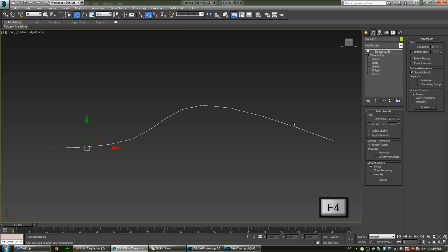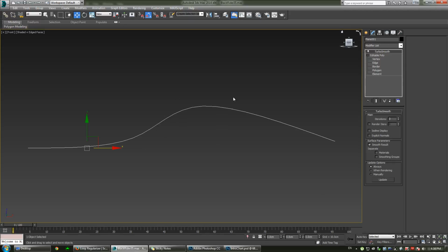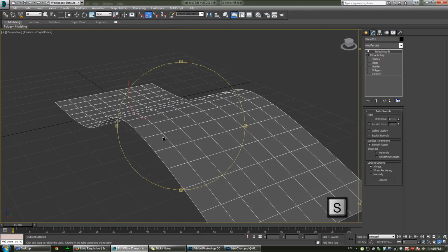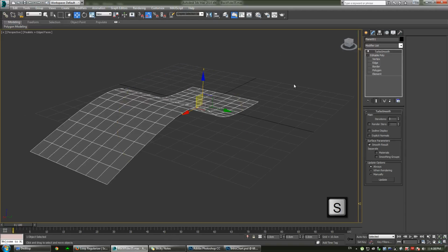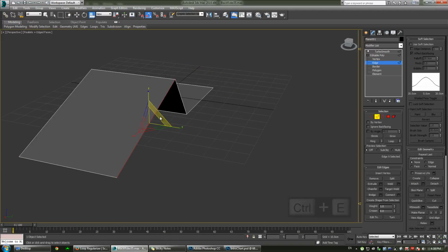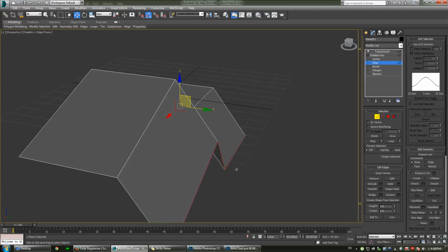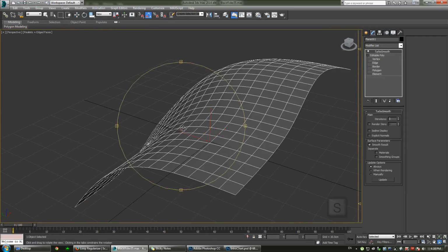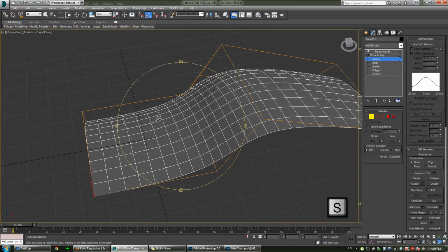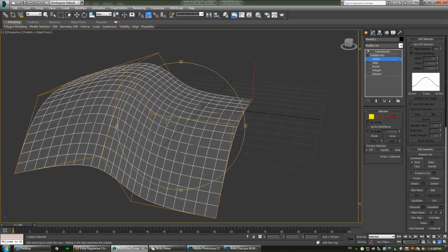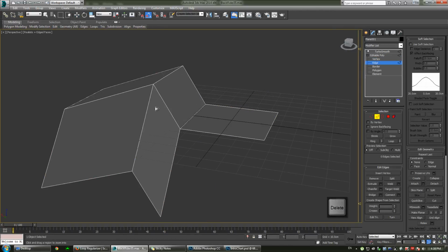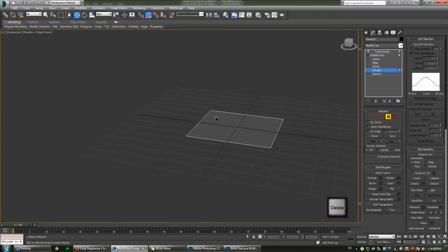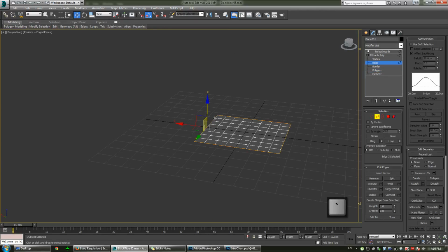And you can see I've got this mesh from side on, and it's just averaging out between those two points. Now what you're seeing there is it's averaging out between 2 points on just one axis, but it will also do it on all 3 axes. So if I double select that loop and drag out, now it's averaging out between 3 points. And this is where the power of edge extrusion modeling comes from: the ability to drag out in real time and see what type of effect you're having on your object.